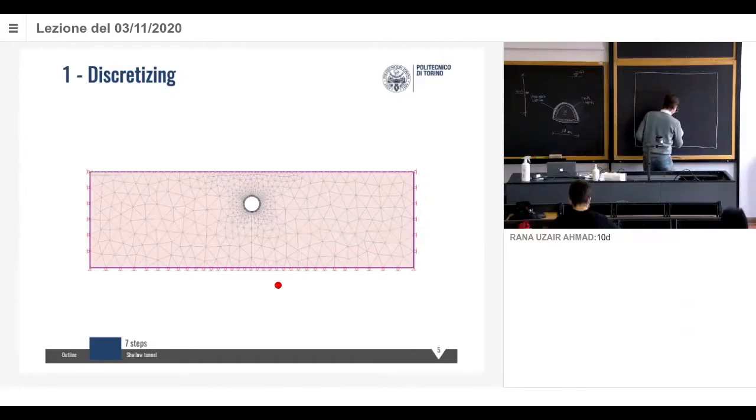So let me put it here. Bigger than 10 times the equivalent diameter. And look, 10 times the equivalent diameter means 140 meters. Okay? So it's somewhere in between the ground surface and the tunnel. But let me tell you one thing. If this was just 100, not 300, but 100, then it would imply that 140 would go above it.